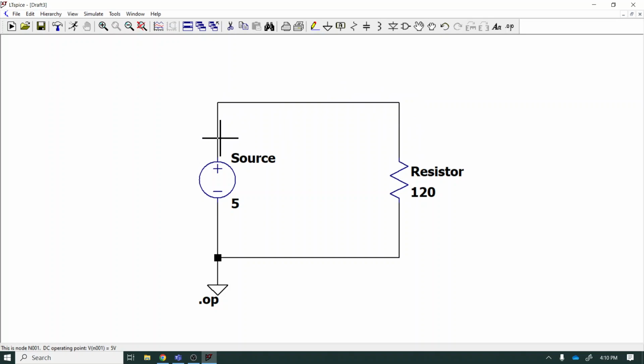Every point in the circuit where you have a wire like this that's connected from here to here, that's a complete conducting path, that's all going to be one voltage in a simple DC circuit like this. And so this is what we describe as one particular node, and that's the identity of it. This N001 is the name that has been given basically to that piece of wire.